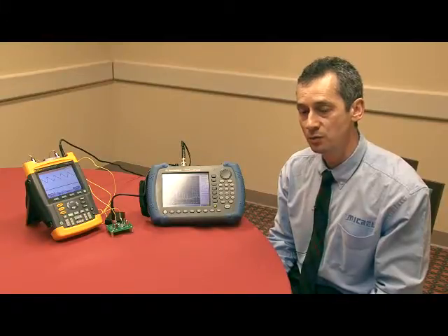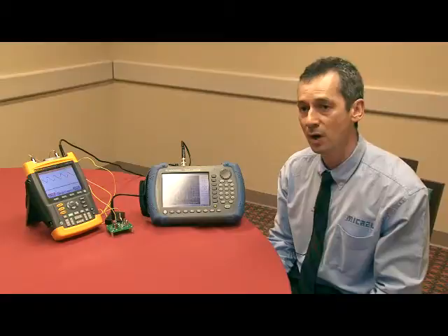It also comes in a very small package, chip scale package, 0.88 millimeter CSP, and also in a thin MLF at 1.2 by 1.6. It only requires a very small ceramic output capacitor and a very small input capacitor, 0201, 1 microfarad ceramic.